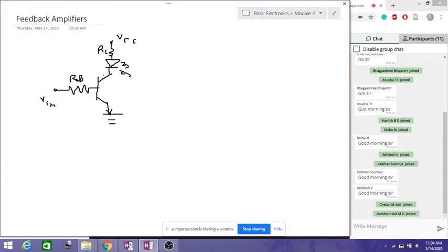To analyze this circuit, it's very simple. Here we are applying the input in the form of a square wave or square pulses. This represents 0 volts and this may represent say 5 volts or 10 volts or anything like that. So it is the same as the switch that we discussed in the previous tutorial. When the input voltage is 0, what happens? The circuit remains open, and the LED remains off.